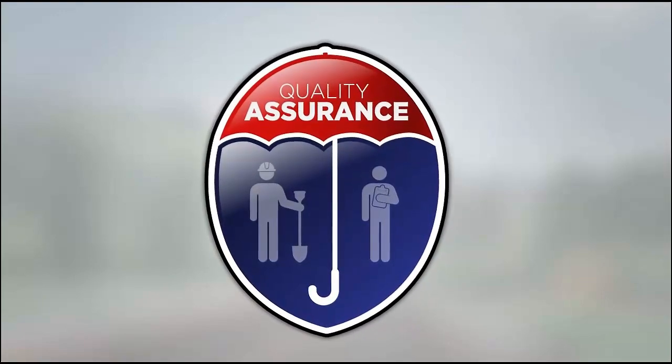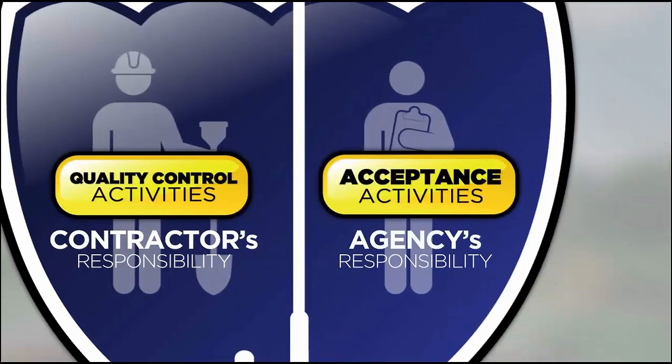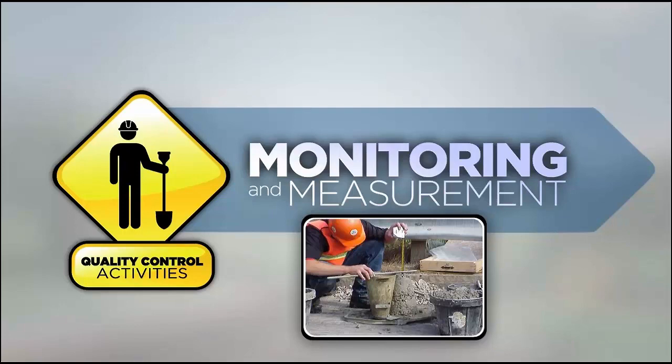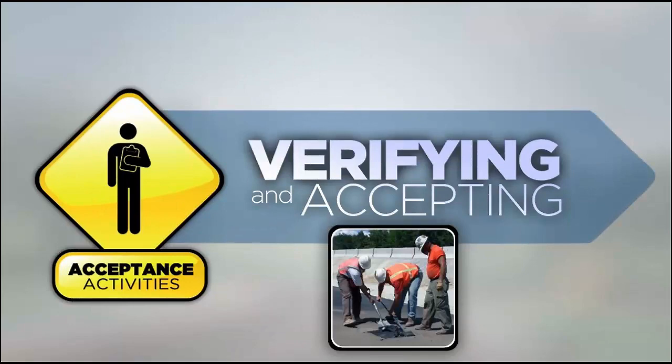Under the umbrella, the basic categories of responsibilities are quality control, or QC, activities performed by the contractor, and acceptance activities performed by the local public agency. The contractor's QC function requires ongoing monitoring and measurement to continually adjust and control the quality. This is accomplished through QC inspection, sampling, and testing at both materials production facilities and at the project site. The agency's acceptance function means taking responsibility for verifying and accepting the quality of materials and construction workmanship.